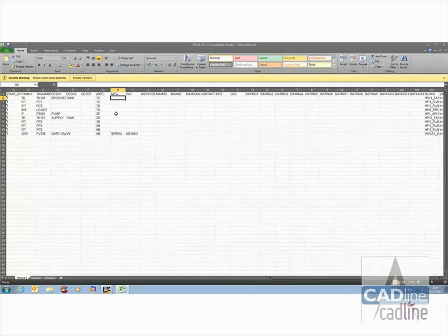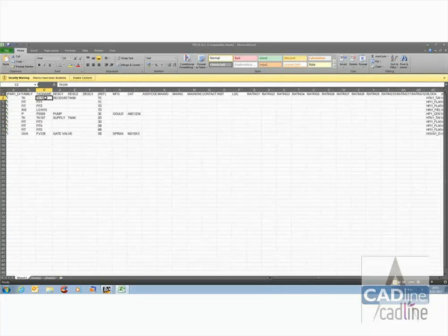So it could be that we know who the manufacturer of the pump is, and by typing in a manufacturer and a product number, obviously it should be a valid part number, but we can, by altering the component tags in here, and we might decide that the component tag for this device, for maybe the gate valve, should be MV5305 as an example.